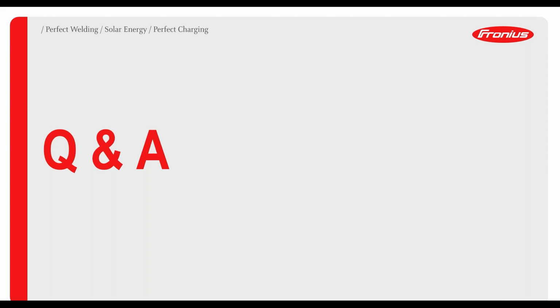So which options are zero export limiting? Yeah, the Intellihub isn't. That's a full switch off. The Fronius internal one is a zero export one. At the moment, the SwitchDin one is a switch off. However, they will be working towards doing a zero export type one. Mondo, I'm pretty sure if they were the CTs, they could do a zero export one if they want to, or the disconnect, they can do both. And then the Watt watches, that's just a switch off one at the moment.